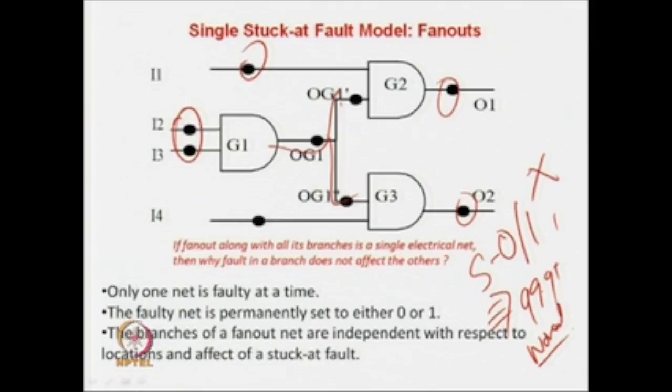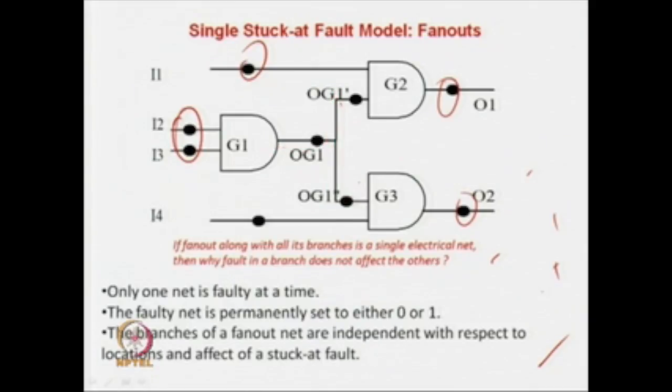But we are not claiming the other way around. We are not saying that if the circuit is normal then there is no stuck at fault; this is not our claim. What we are saying is that we verify the circuit has no stuck at faults, and then there is a 99.9% chance that the circuit has normal behavior. So if we treat this as a single net, it has been found from the statistics of history that the accuracy is lower. So we have to also consider this as an individual net and this as an individual net. So basically this is a model. In reality, circuits do not have stuck at faults.